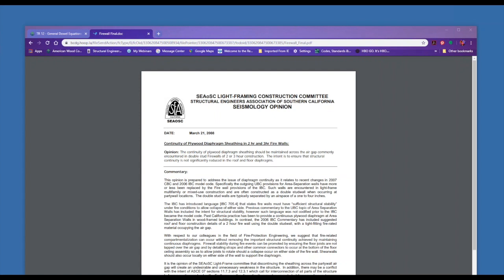That being said, the fastener head pull-through provisions will apply to any round-headed fastener, so they would work for a carriage bolt. However, the NDS tables, the bolt tables, especially for lateral connection capacities, would not be able to be used with carriage bolts. So you do want to make that distinction. The carriage bolts are different than the bolts that we call out in the NDS.